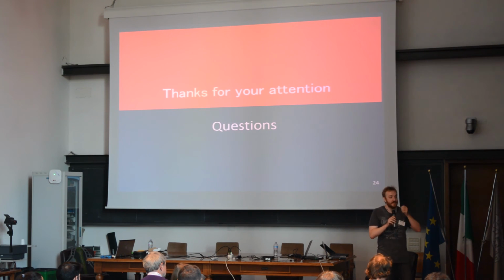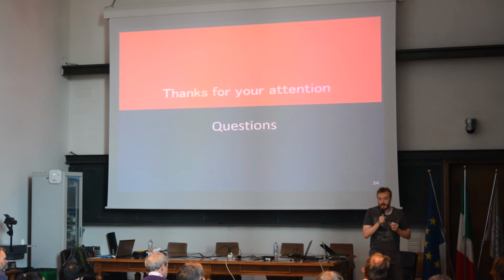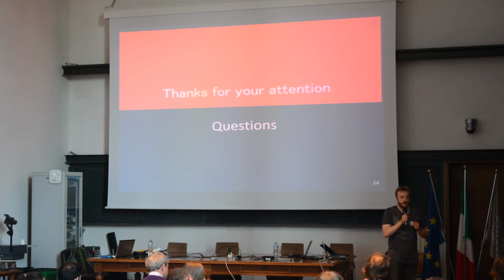Sorry. Memory consumption is 2 to the power of history bits number. So that's the result of a 93% hit rate for Dhrystone. I think we got it with a history size of about 12 or 11 maybe.